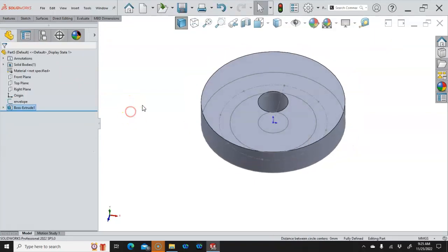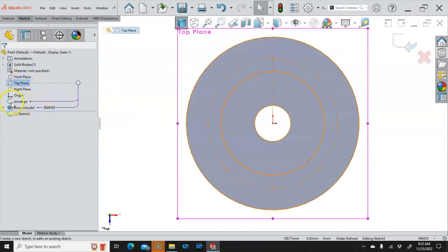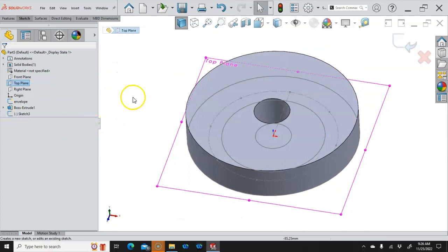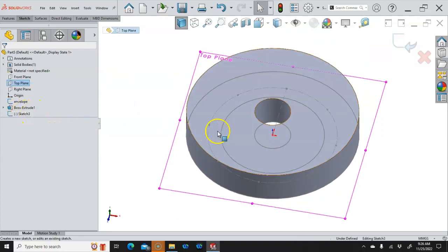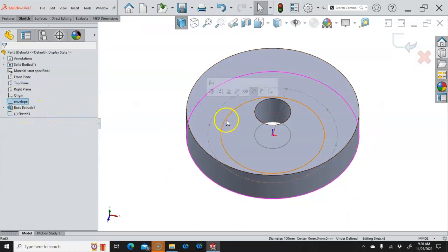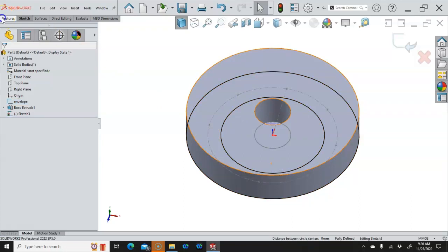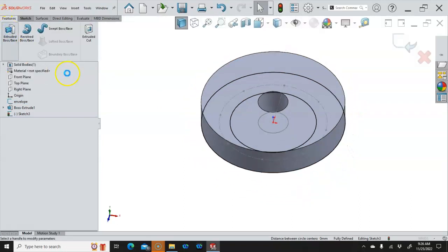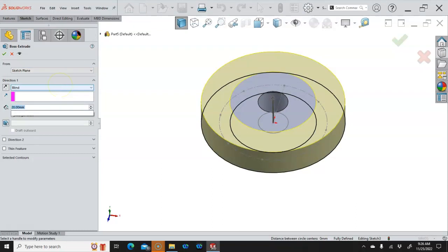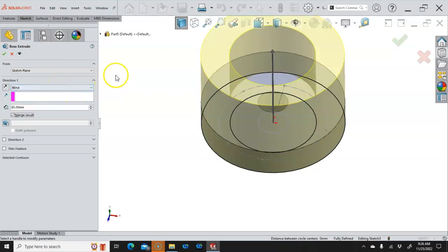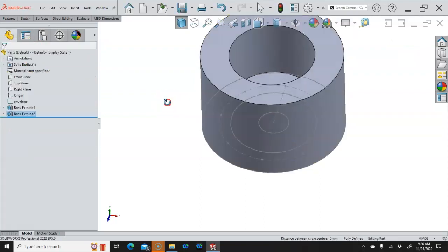Okay. For the next one, we'll open up a sketch on the top plane. The envelope is still shown. One of the things that would happen with the shared sketch is it would hide that sketch, and then we would have to show it and pick in the contours and regions. So here we've opened up the sketch, and I'm going to control select, convert, and then an extrude positive through a positive is just no net gain. So if I go to the 65 millimeter height, then we can accept that.